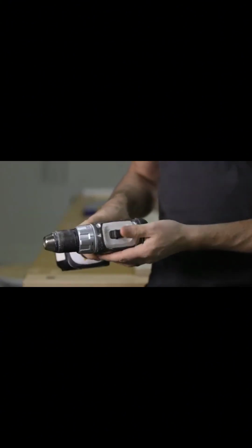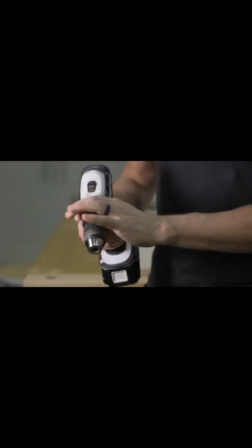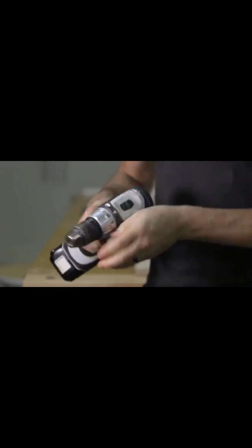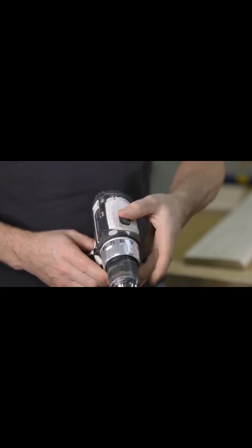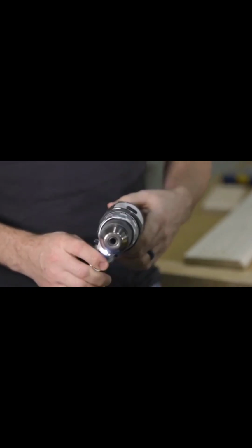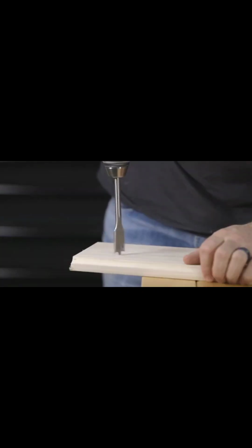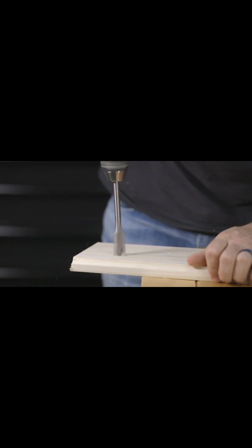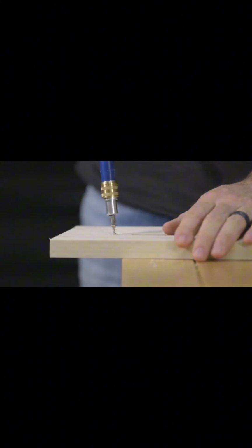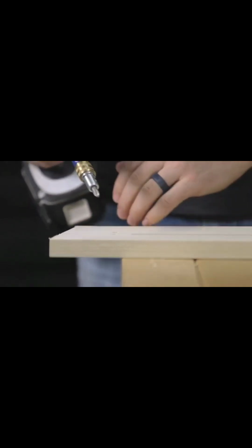Most drills come with two main features, the gear selector switch and torque control. The gear selector switch allows you to have control over how fast the drill spins. Number 1 sets the drill at the lowest speed, and number 2 at the highest speed. Why is that important? Well, it gives you more control over specific tasks. For instance, if you're drilling holes, more times than not, having a higher bit speed is ideal. But on the other hand, if you're installing screws that are small and require a little bit more caution, having a lower bit speed would be more ideal.